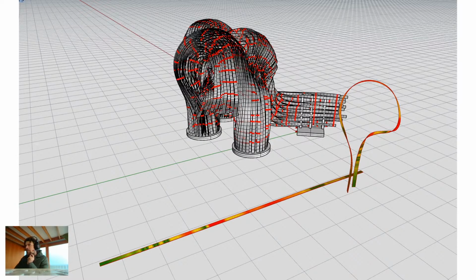And this is a kind of a key idea. It's being able to form very, very simple standard pieces of material into very, very complex, unique shapes without generating any waste at all, and keeping a very short production chain, which keeps things very flexible. So if for any reason we did break apart, we would always have more material ready to reform into that same part again, again reducing our risk. Whereas if we had to CNC cut anything, we would have to reproduce our cut files, send them off to the fabricator, get them cut, wait for them to come back, and then rebend them. And again, we just didn't have that kind of time.